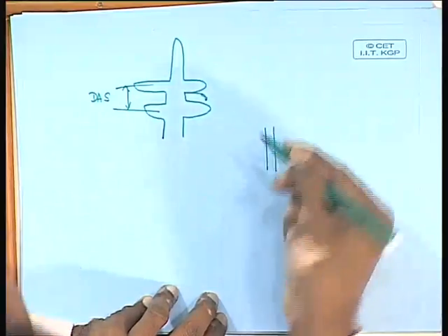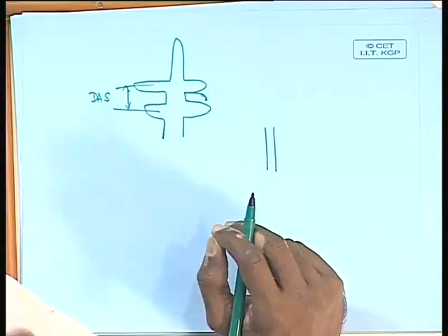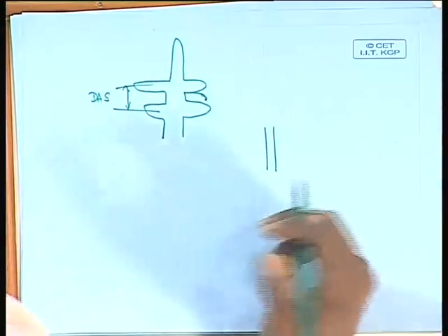Similarly, if you look at the eutectic microstructures, if you take a eutectic composition and then try to solidify, there is what is called interlamellar distance. Whenever there is a lamellar eutectic that forms, there is an interlamellar distance between any two lamellae. For example, if you look at the pearlite, which does not really form from the liquid anyway, we should not consider that. But if you take any simple microstructure such as aluminum copper, it is a dendritic, a lamellar eutectic.